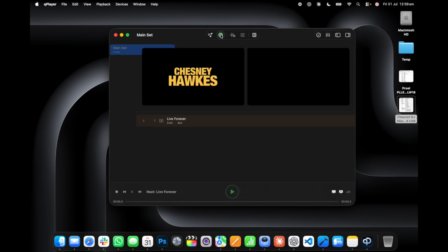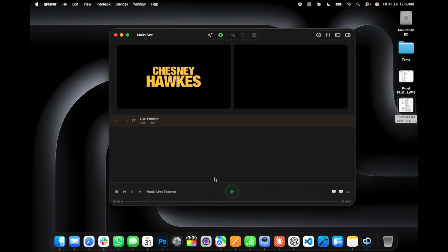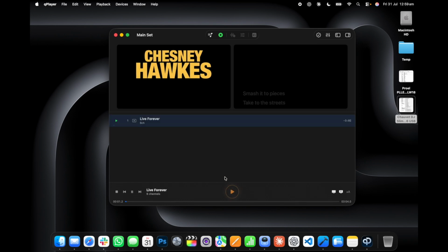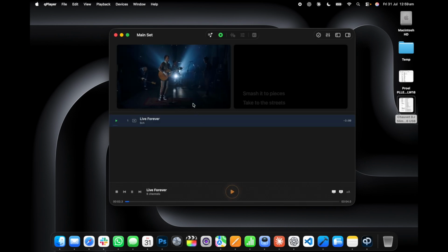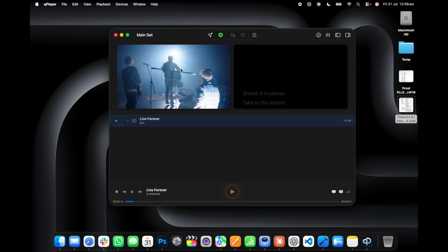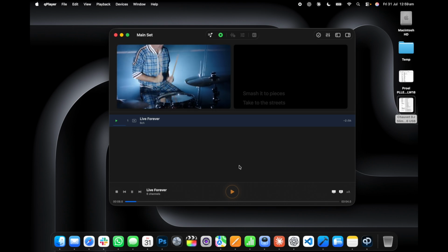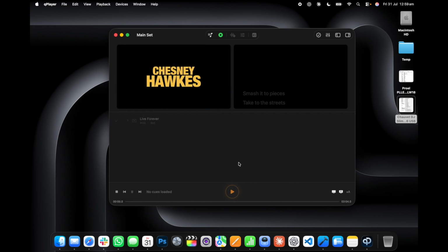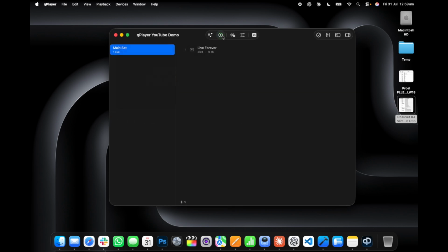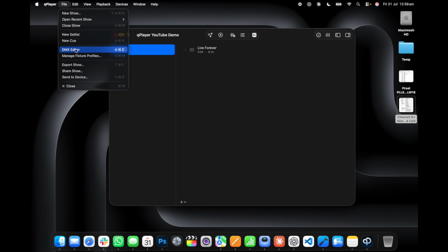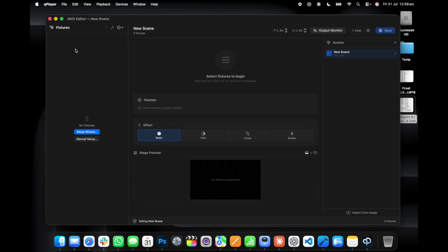So if we just resume that show, if we remind ourselves what we were looking at, if we go into show mode, it was one track. If I hit play, we can see what we had: 1, 2, 3, 4. So we had a 6-channel audio track, video, and also auto cue. So if I just stop that one, come back out of show mode. So what we're going to do is we're going to add DMX. So we go up to the file menu and click to go into the DMX editor.